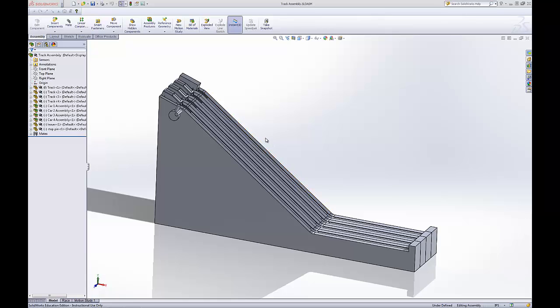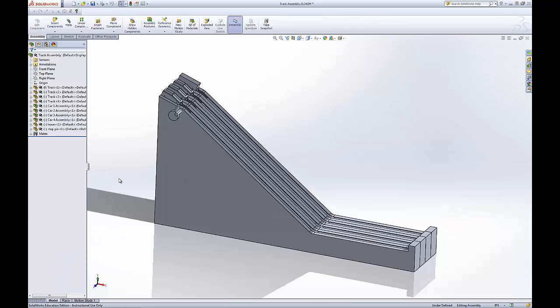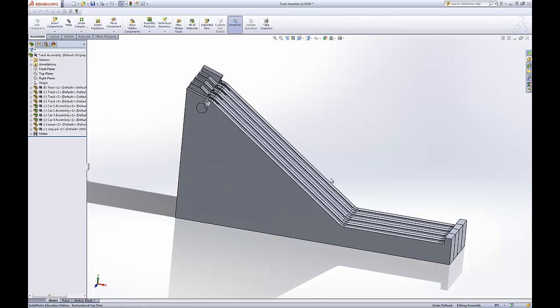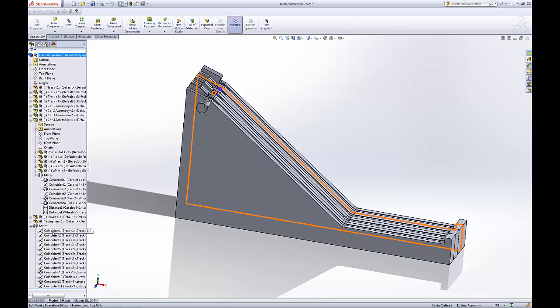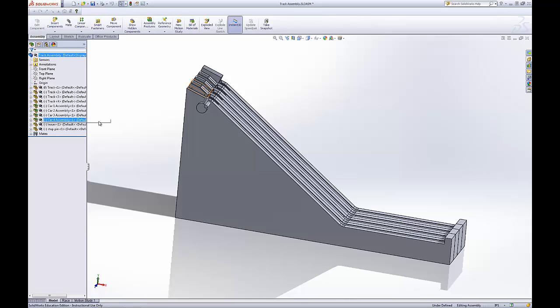So, you can see here I have a racetrack that we can do a motion study on and have it run down the track. That'll be another tutorial, probably in the series. But at first we're going to focus on the power of the assembly. As you can see here, I have assemblies inside assemblies, which all have mates, and even this assembly has mates to specific entities. So with the car assembly having constraints with the car, and then the track having constraints to the car, they can get pretty complicated and get you really long design trees pretty quick.